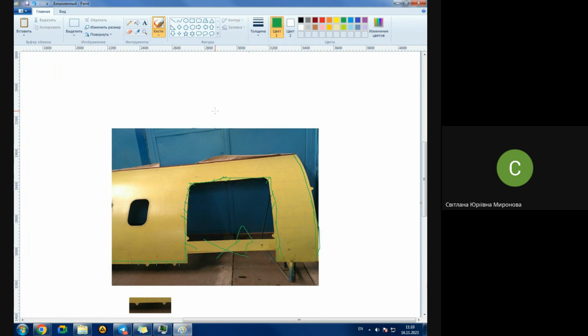Here, in contrary, in order to be sure that during manufacturing, even if we make mistakes somewhere, we have not spoiled the whole panel of aircraft or the whole compartment, we have not made something shorter. We would rather make it longer by a couple of centimeters, and we lose this couple of centimeters of material, like it would be sent to scrap. But we are sure that we have not spoiled the whole panel.